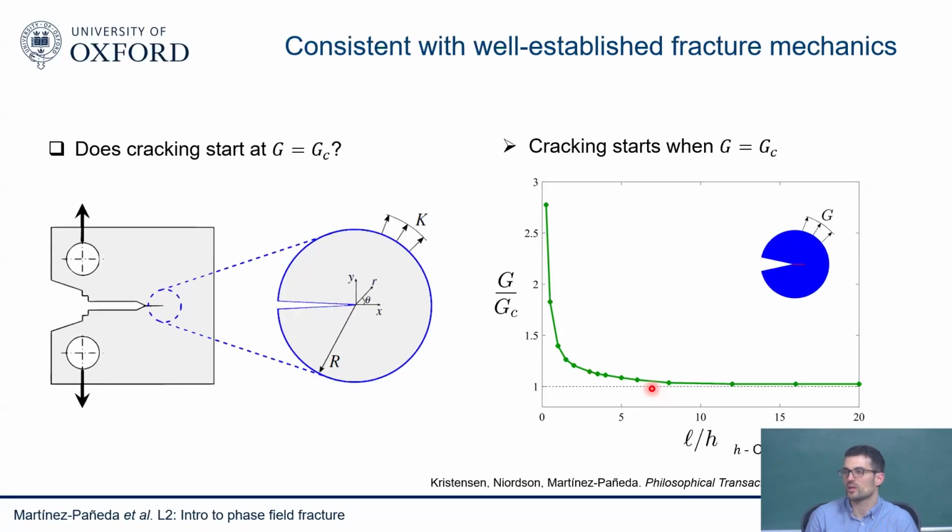Normally a rule of thumb that people will take is 5 times. If you use an element size that is 5 times smaller than the length scale, you are safe. In the first papers, people were taking 2 times, which is I guess somewhere here. It's not too bad, but I will feel a bit safer with 5 times. So you still see a lot of people in the community taking an element that is half the length scale based on those papers, but based on this type of results, I'll feel more comfortable with 5 times. And for analysis, you are actually computing L from the previous formula that you showed? Yes, I'll normally do that, yeah.